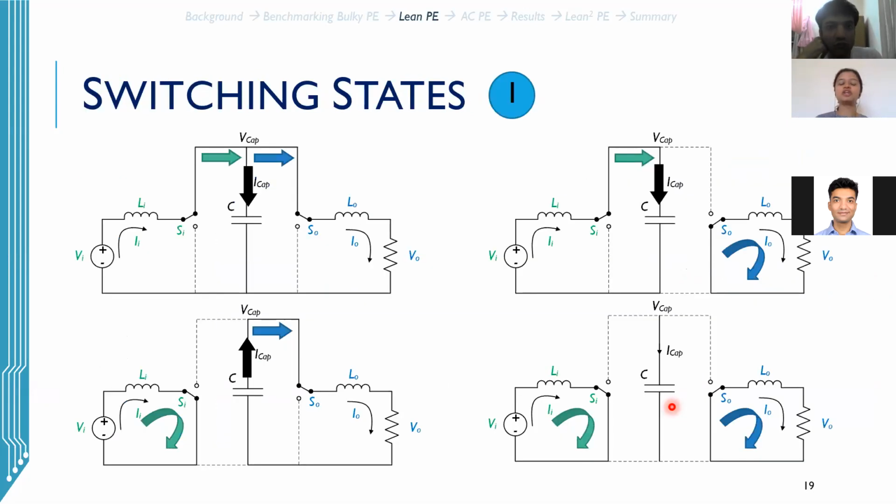So we are looking at a DC to DC power converter example, wherein we have 2 switches. This means that we have 4 switching states, which are as shown right here. One of the states is when both the switches are connected to the DC bus, and only the net difference in energy is flowing into the capacitor. The other extreme is when neither of the switches is connected to the DC bus and we are freewheeling. The intermediate states are shown as these 2.